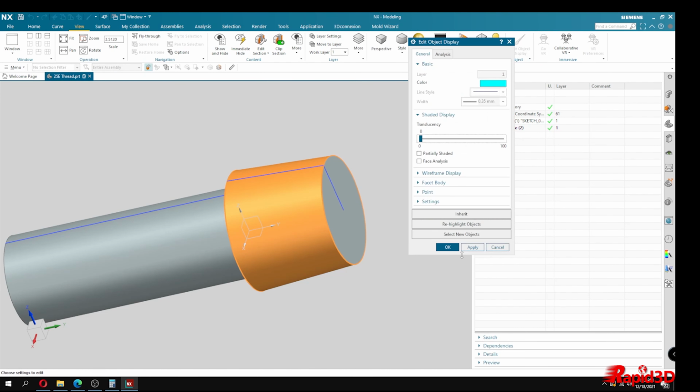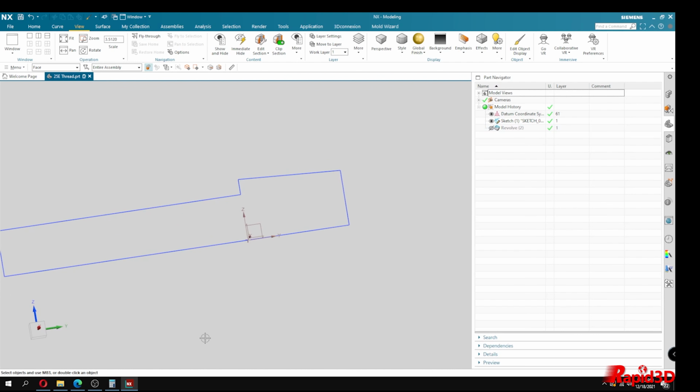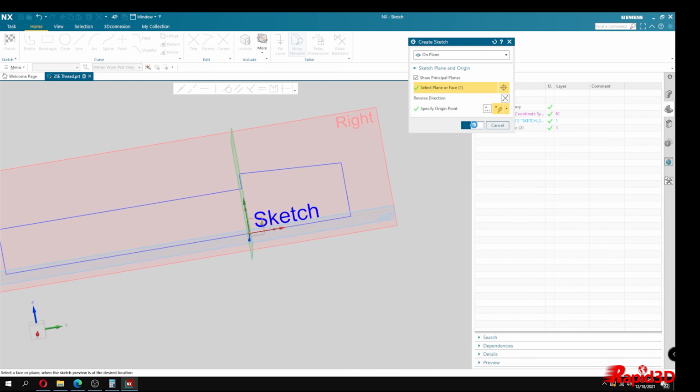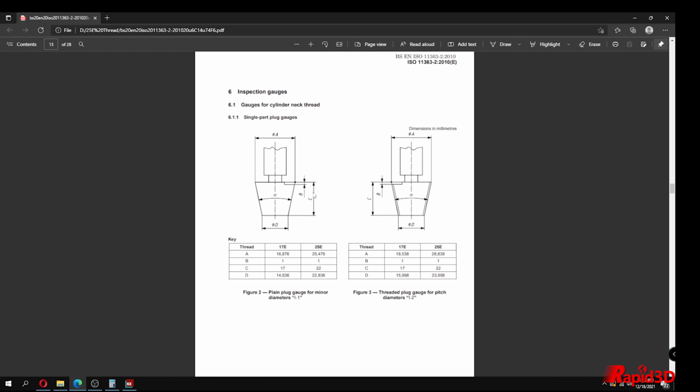In the datasheet you can see the minor diameter for the threaded section. There you also need to draw the minor diameter tapered line in the sketch, because in NX turning CAM we need it later in order to provide the taper angle.